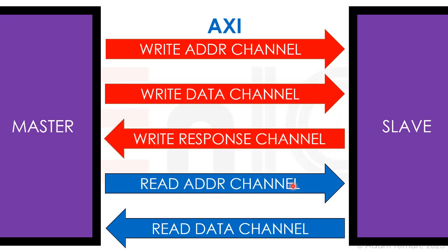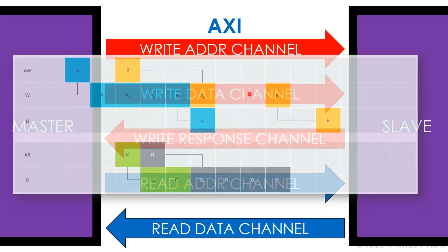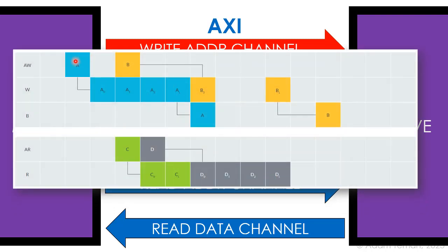So really all of these types of ACKs and NACKs can be done separately on each of these channels. Nothing has to be ordered, and we can get this really nice ordering over here where this is kind of in order, but you see that we have transactions on the address bus, we have transactions on the data bus, and these all happen before we actually get the confirmation that the data was actually written. And in the meantime, we also sent out read transactions at the same time and got the answers and so forth. And this can be mishmashed around to do any kind of ordering we want. And the DDR controller can therefore play around with this to maximize the throughput to the DDR. So that's why we have such a bus like the AXI.